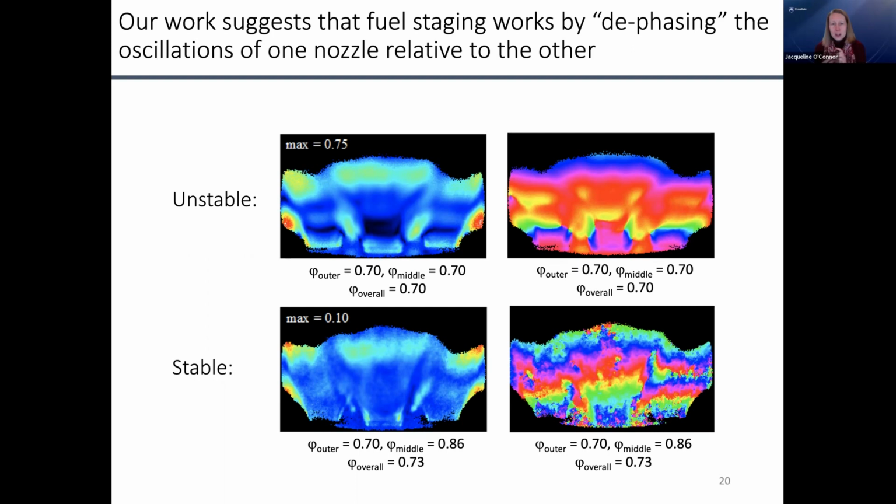We use spectral POD a lot, the method from Towne. So we use all of that in cases where you have to kind of pick out the instability over other stuff going on. For these experiments, particularly in this multi-nozzle case, this thing is screaming so loudly at just one frequency that the rest of it isn't super necessary. The FFT, you know, acoustics are sinusoidal. The FFT is the right decomposition to use.